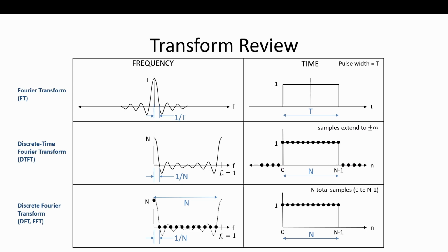Sampling in one domain makes it periodic in the other domain. It'll keep the spectrum, what you have here, repeating at every multiple of the sampling rate. So that's why you'll see it. If you've seen an FFT, you see it goes out to half the sampling rate and you keep going. And if it was a real waveform in time, it repeats again exactly. And then if you kept going, it would be mathematically equivalent to it being completely periodic. You'd get the same result.